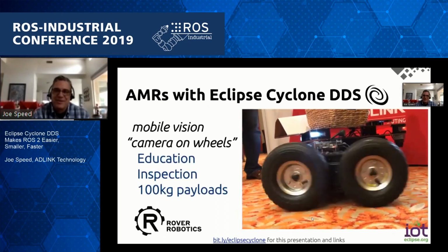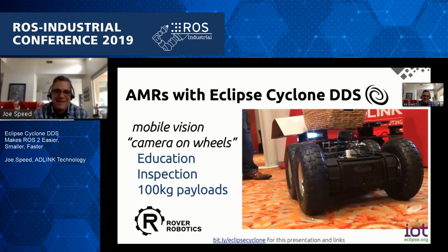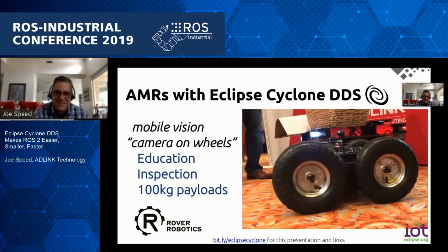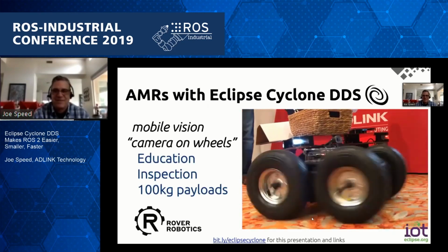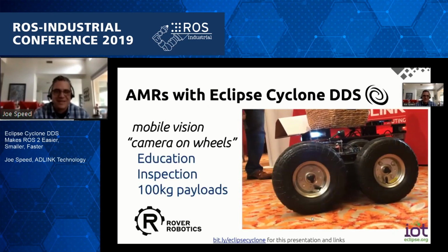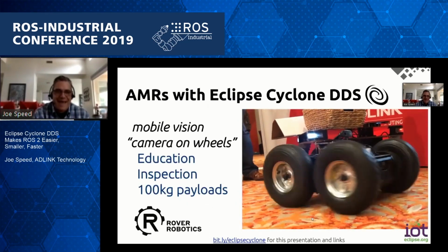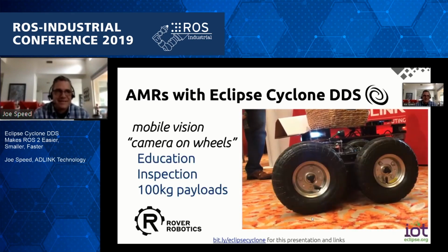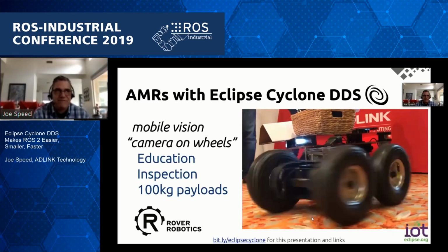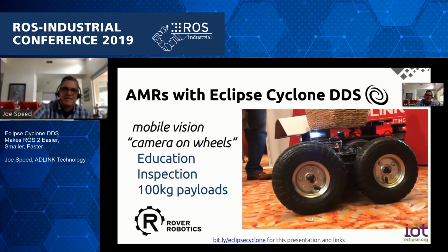They make this little workhorse, this little mule of a rover that weighs 17 kilos and carries 100 kilos. It's IP67, so you can drive it across streams and through mud. If it gets dirty, you hose it clean. It's drop tested from two stories. It has titanium axles, and they start at €5,000, I think, something like that. So it's a pretty amazing price point.